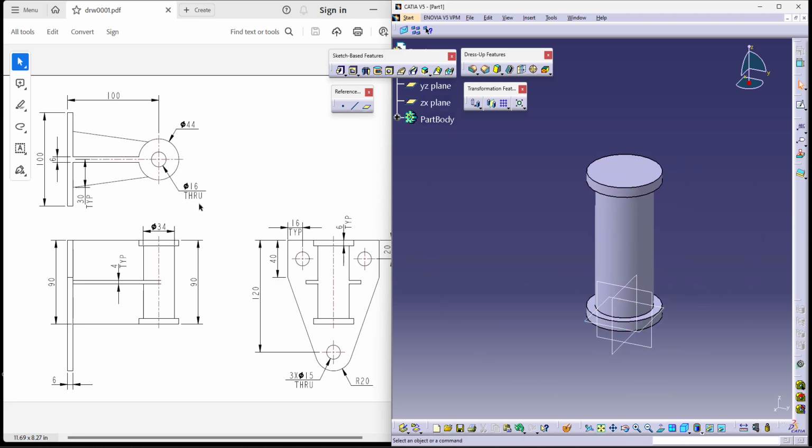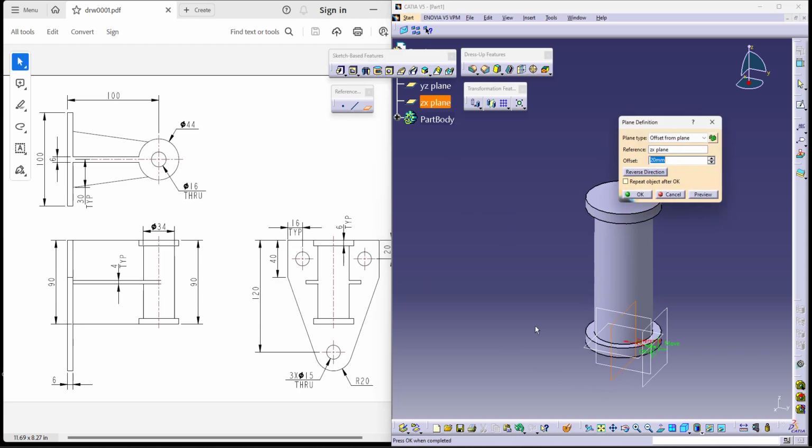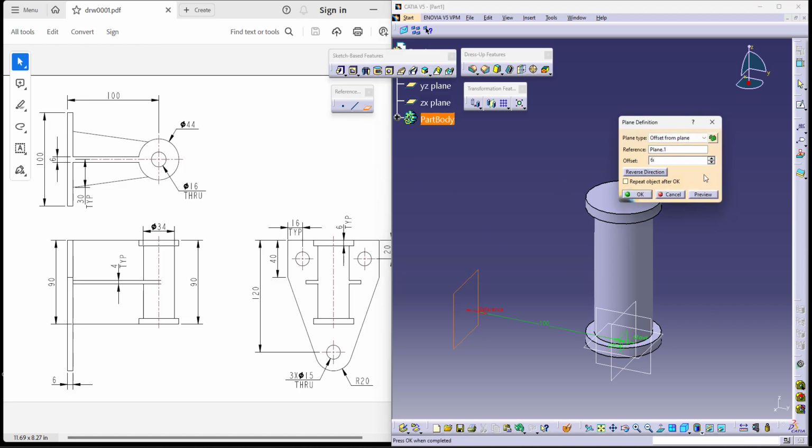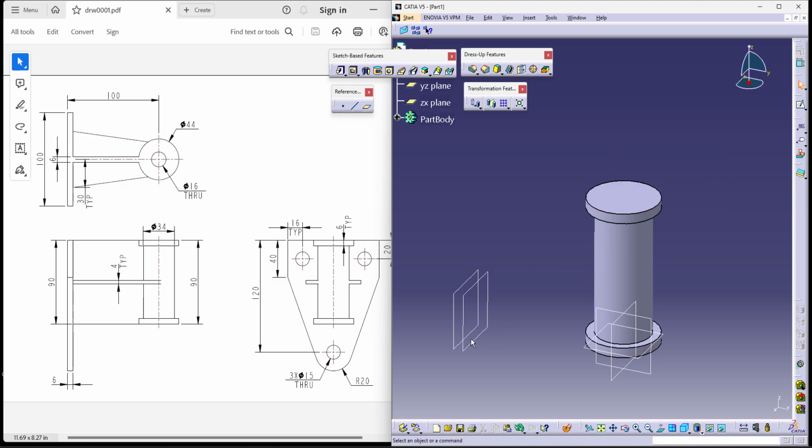Now, understanding the feature based approach and maintaining the constraints and following the process, to make this, first we need to maintain 100 and then maintain the plate with length, which is 6. So first, to do so, let's try to take our references. For example, from here towards the opposite side, I have a plane at 100, and the feature whatever is starting is not actually starting from 100, but it is starting after the plate. The plate is actually 6, so let's try to take another plane and give it 6. So I'll be making the feature on this plane rather than on the edge plane.